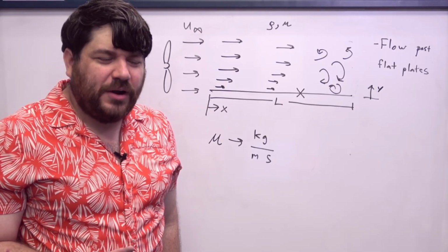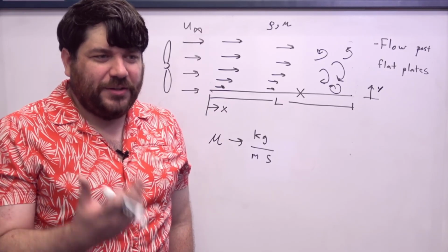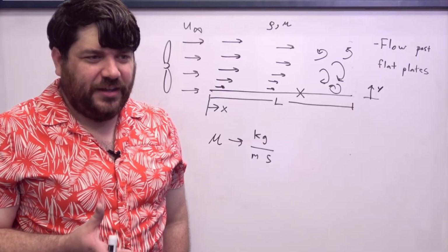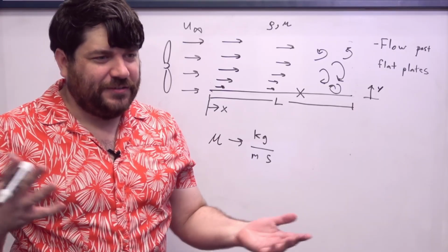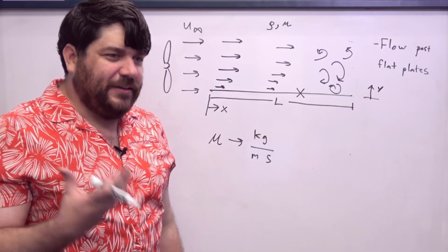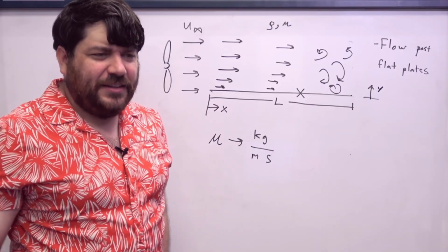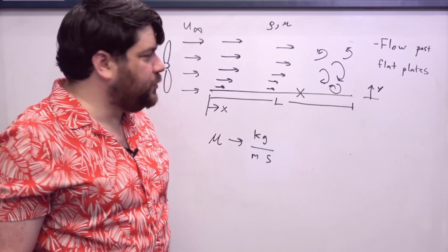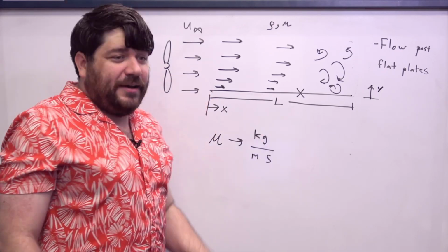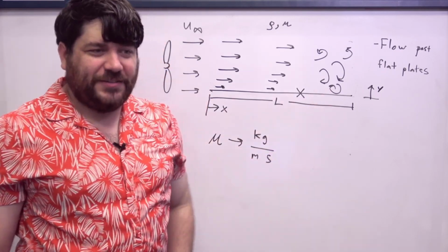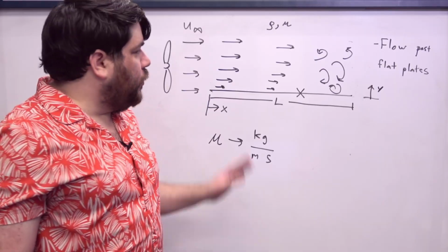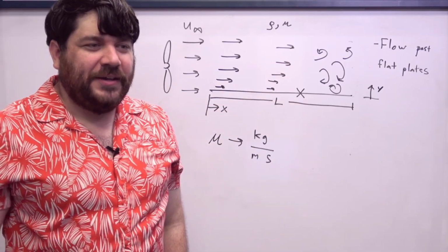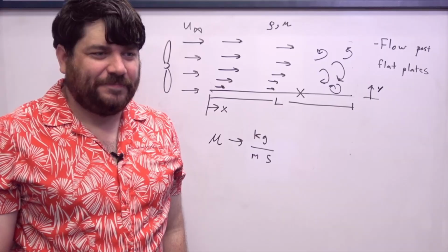And this phenomenon is called turbulence. And this creates a problem because very often what we do is that we assume that a system is in steady state. We give boundary conditions, and things like that make us think, oh yeah, the system is in steady state. The boundary conditions are in steady state, so the system should be in steady state, right? Like we should find a solution for it. But we find that even if we have steady conditions, we have unpredictable, unsteady behavior for the dynamics of the fluid past a certain point in the plate. Okay?